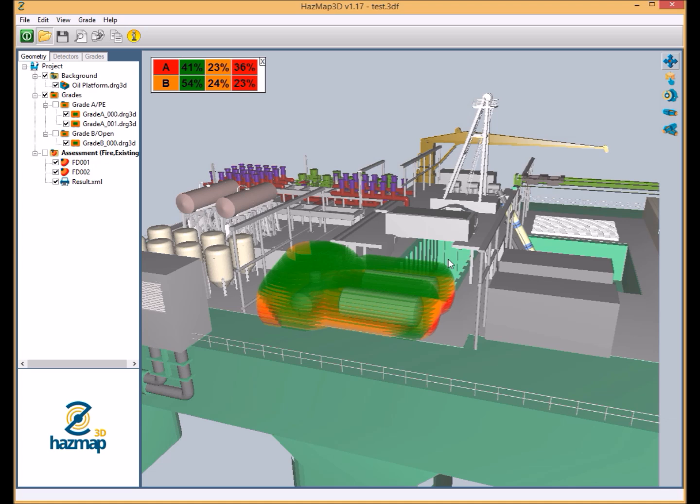At the end of the day, it's important to remember that any material in the gaseous state represents the ultimate expression of disorder, and by definition will fill all available space in which there is a random distribution of molecules or atoms. As such, where modelling of any form is to be used in determining the layout of gas detectors, dependent on the application of course, it's reasonable to suggest CFD explosion modelling should be the only tool used as an input to the gas detection mapping process, although this is not always the case.